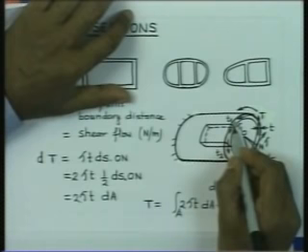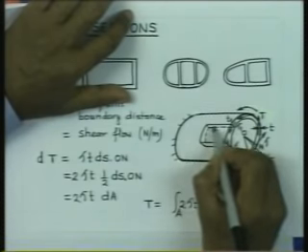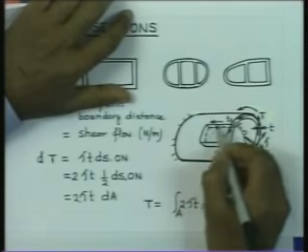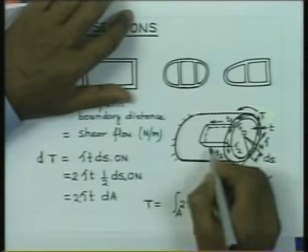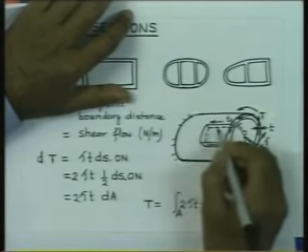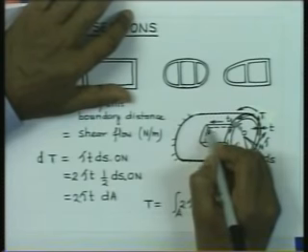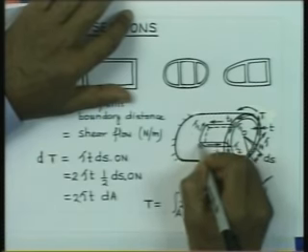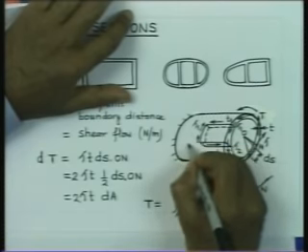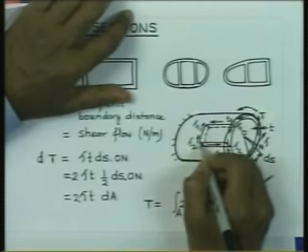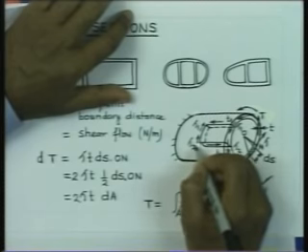Since the shear stresses are acting on this face, on the perpendicular face here, we must have shear stresses acting like this, which is again tau 1, and shear stresses that are going to act here on this face are going to be complementary to this stress, and this is tau 2. Simultaneously, we will have the shear stress acting here in this direction, it is tau 1, and the shear stress at this point is going to be tau 2. So, on this face you have intensity of the stress acting in this direction is tau 1, and intensity of the stress acting in this direction is tau 2.